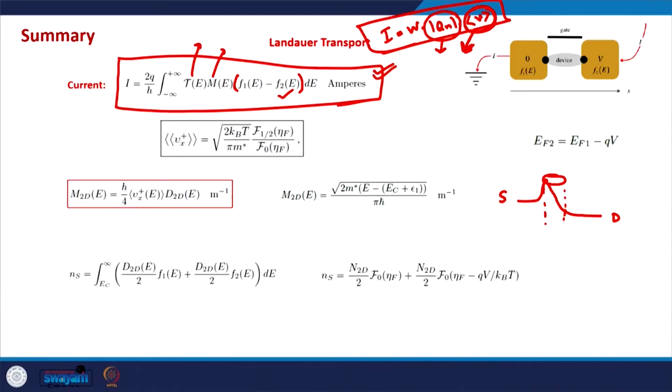So, in order to do a proper calculation of the current, we cannot separately calculate the velocity and separately the charge. They need to be considered together, and the actual calculation of the MOSFET involves the calculation of the drift diffusion equation and the Poisson's equation, and if we are doing the quantum mechanical treatment as well, the quantum mechanical equation of transport, self-consistently. That way we are able to get the entire picture.